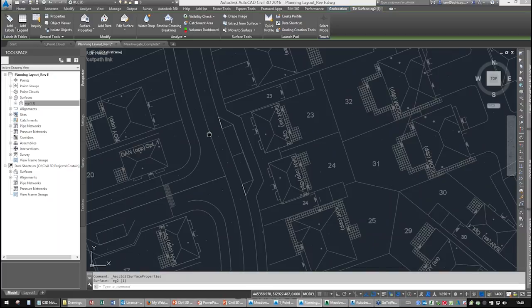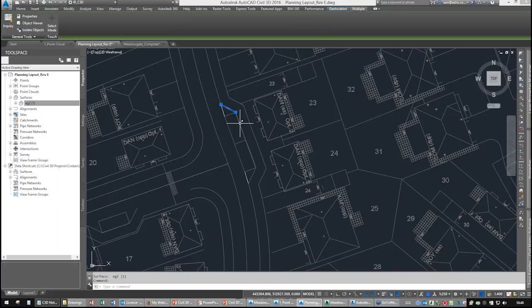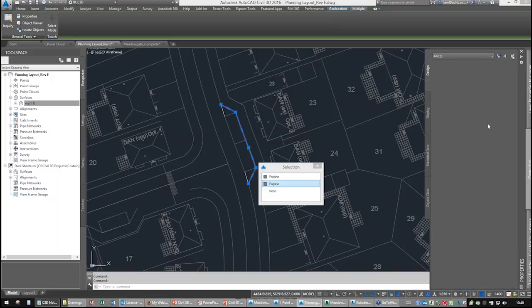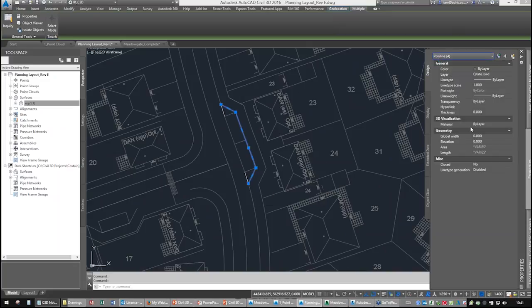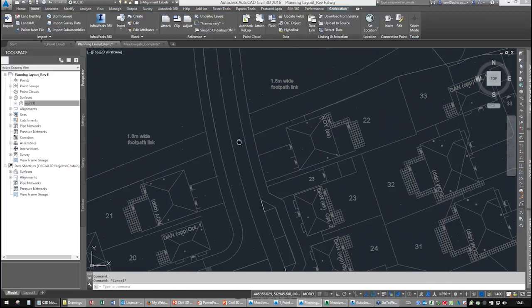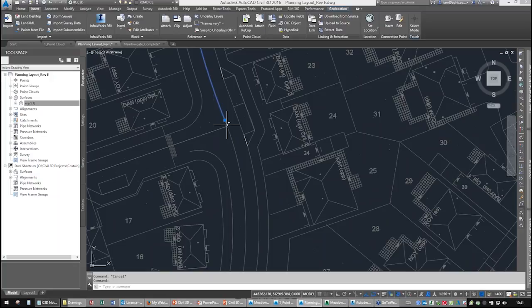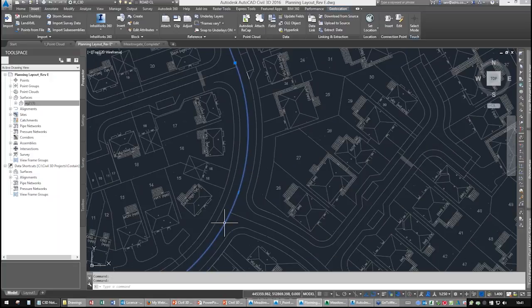And what I wanted to show you in addition to the basics was simple widenings, etc. So we've got a widening here. So this is just a parking bay, a 2-car parking bay. You can see they're all done in polylines. The properties of these polylines, if we have a look at them, you'll see that there's no elevation to them. That's okay. We haven't got a 3D drawing here, it's just a 2D drawing. So the first thing is we're going to take an alignment from here and create this as our road number 1.